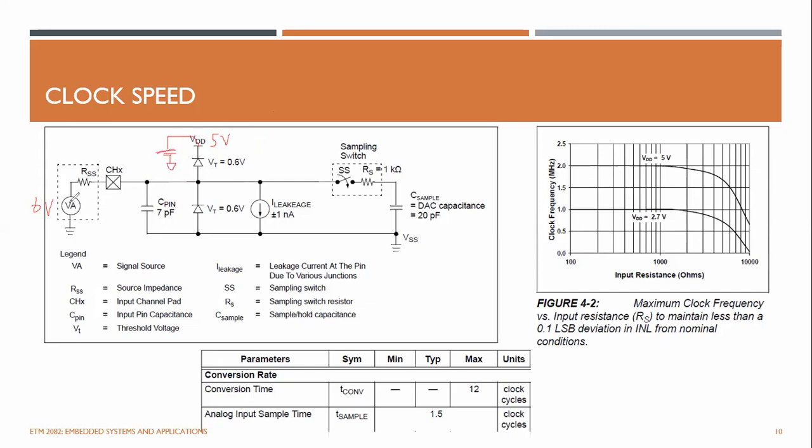Okay. And 6 volt is higher than 5 volt, so definitely the current will flow from this part to the 5 volt line and charge this battery and return back to the ground. And this is also ground, so they are connected together, and it makes a circuit completed. So as this is 5 volt, there's a voltage drop across the diode. They say it is 0.6. So this point voltage will be 5.6, right?